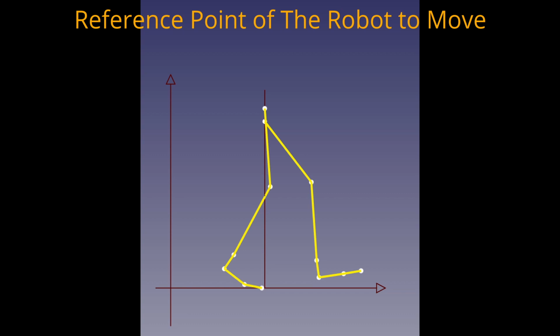Because I assumed this human robot to move horizontally in the x-axis direction in the 3D space, I designed the x-coordinate value of the upper end of the right leg to be the same as that of the left leg. And I set up this value on the x-coordinate as the reference value. Changing this reference value means the 2 upper ends of this robot's legs move horizontally accordingly.